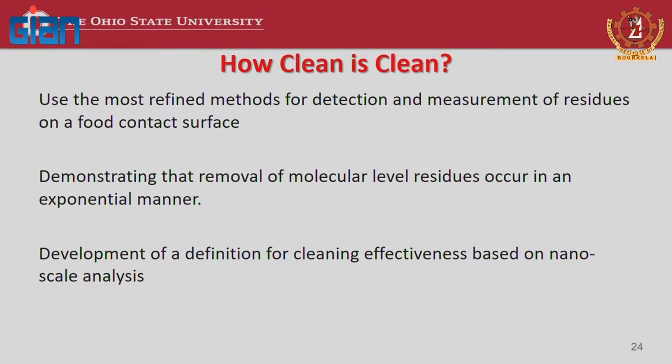So, how clean is clean? The cleaning, basically, you have to look at the molecular level residue. For example, there are some specialized things you can do, like a swab test on the surface being cleaned, and then analyze this with certain quick methods to see how much residue may be there at the ppm level or even lower. So, you are able to say, okay, this is an acceptable level and so on.